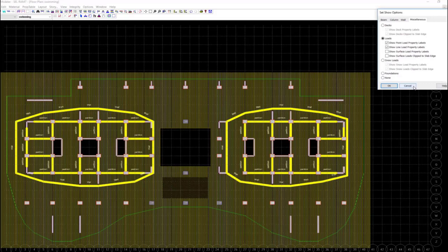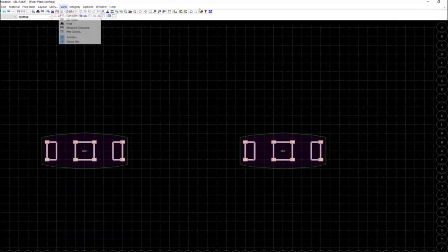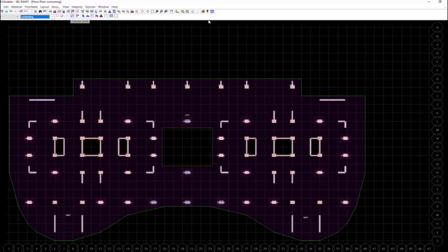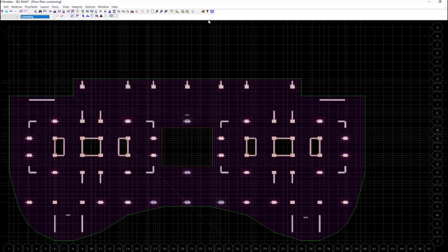The quick way is by using the construction line. In case you come across a situation like this where the boundary node of selection doesn't coincide with the regular grid, then you can add the intermediate grid line dynamically. I could switch it off later on. This facilitates me to select the intermediate nodes for creating any shape of the partial pressure loading or the line loading.